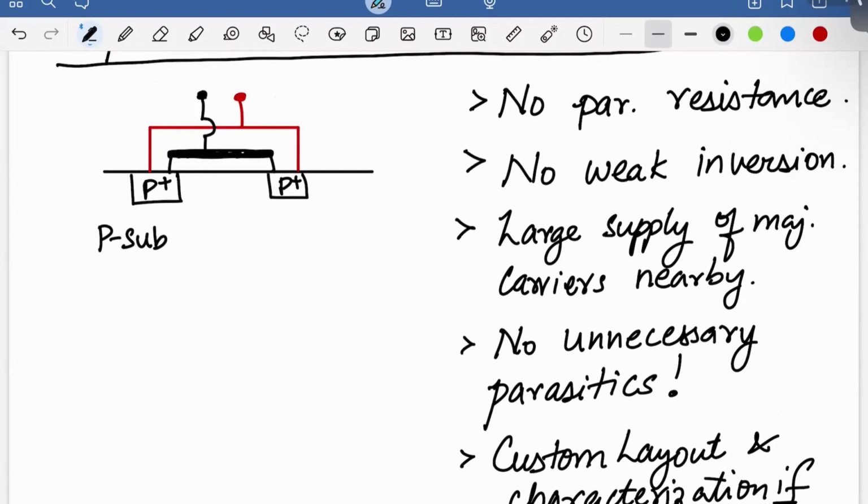Okay, we can actually slightly improve this even further. One minor issue with this is that in this case, the majority carriers are holes, right? Because that's what is supplied by these, remember that accumulation mode only happens when the voltage is less than zero. And holes are slower. So in fact, it's better to use a PMOS version of this. So what does that look like?